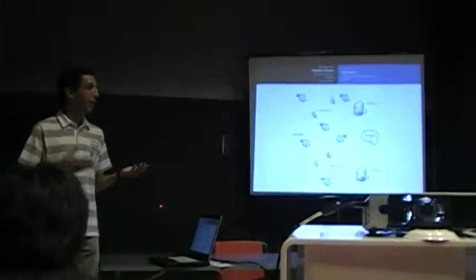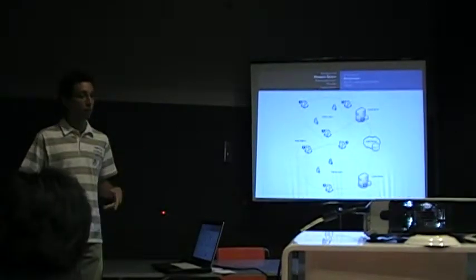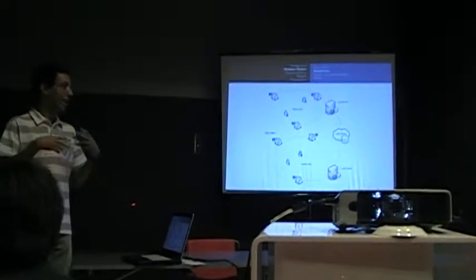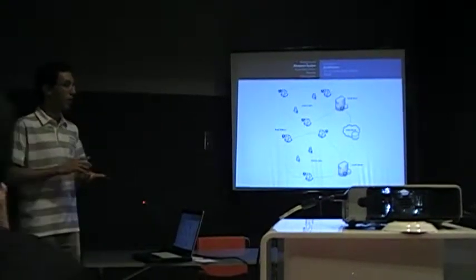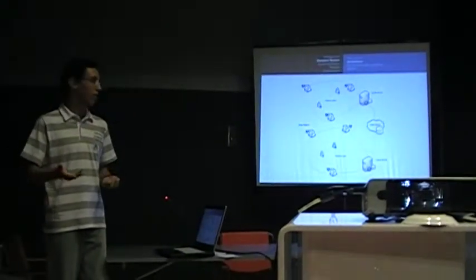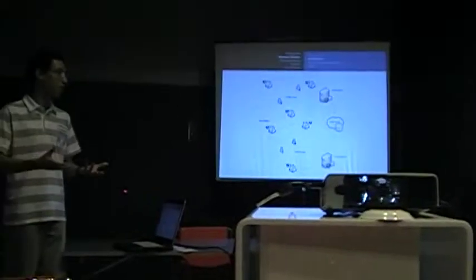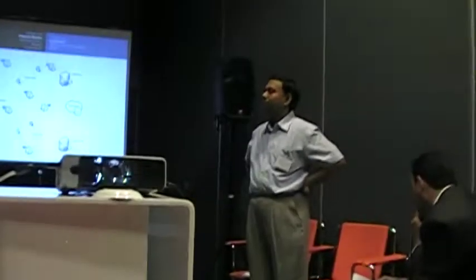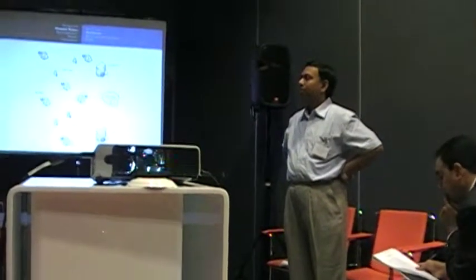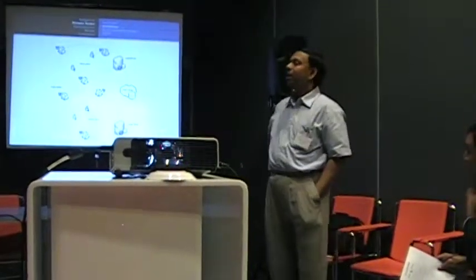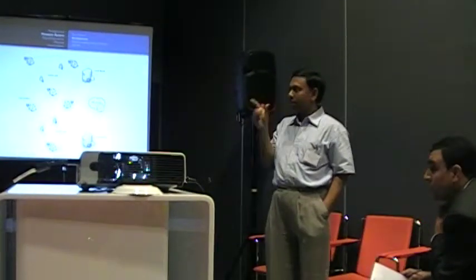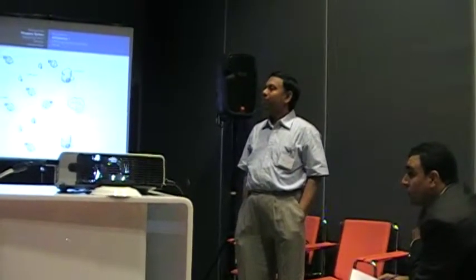Okay, like we said, we did some regressions. By having the RSSI value and the distance, we can try to create a formula from that, a regression, and the formula is going to be something like the ITU formula: when you input the signal strength, you will get the distance. So the data collection was actually to calculate that formula, based on real data. So that's the relation in the regressions. If you have a strong signal strength, what would be the distance? Shorter, because the stronger the signal is, the closer you are to the station.